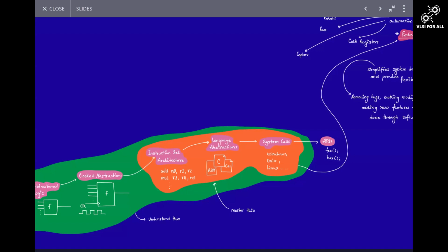Basically, what I'm trying to say is that the first thing you need to know within an RTOS is task switching. In how many ways can you switch between tasks? You will have something called priority for a task. Whenever a higher priority task is running, you cannot switch it to a lower priority task. So based on this priority, there are different mechanisms of switching between the tasks. You need to understand it.